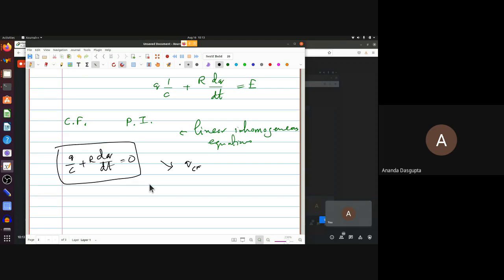So the actual solution to this problem is always a sum of two terms. One is what you get using these complex impedances and so on. But that's a particular solution to the differential equation, not the full solution. The full solution will have that plus the complementary function piece. But the question now is, if that is the case, then why can we get away by saying that E equals I into R plus 1 by j omega c? That's what we do, right? When we analyze an AC circuit, that's what we always say, or at least almost always say.